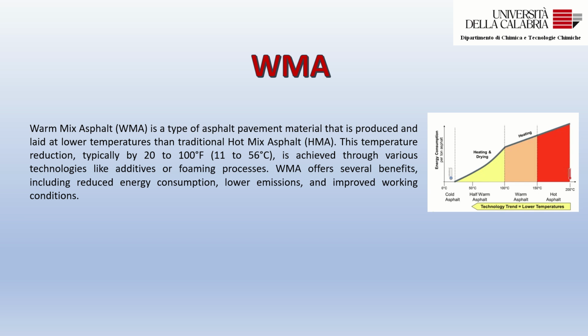There is some technology we call warm mix asphalt, using additives, in general surfactants, the new generation of these compounds, that reduce the viscosity of the asphalt concrete, so you can process the system not at 180 degrees, but for example 120 degrees. In this case, you save energy, and you use an environmentally green process. Consequently, the government and the stakeholders push in this direction to find new compounds that give this property to the asphalt concrete.